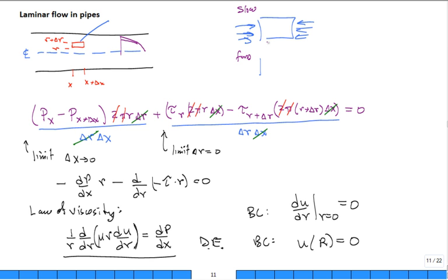Hence, you're going to have the faster flow trying to motivate, through viscous effects on this bottom side of that element, in the positive X direction, and on the R plus delta R surface, it's going to be slower and have a viscous effect in the negative X direction. See that? Now, this is a two-dimensional cut, but what does that really look like? It's revolved around that axis, right here.